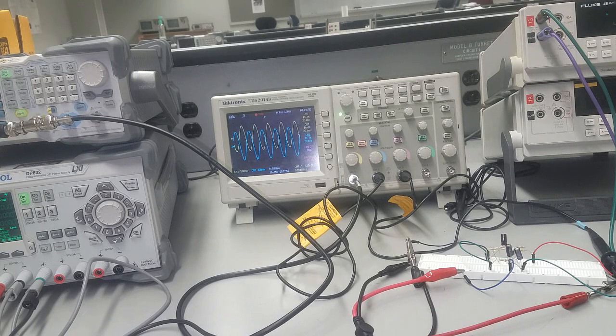So we decided to do it using trial and error. We said let's make RS 20K. When we did that, the current dropped to half, which means GM dropped by a factor of 30%. It turned out that the gain dropped dramatically: we got a gain of 35 volts per volt. We didn't meet the specs.